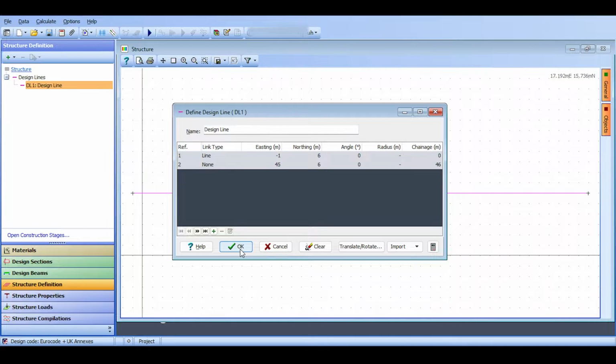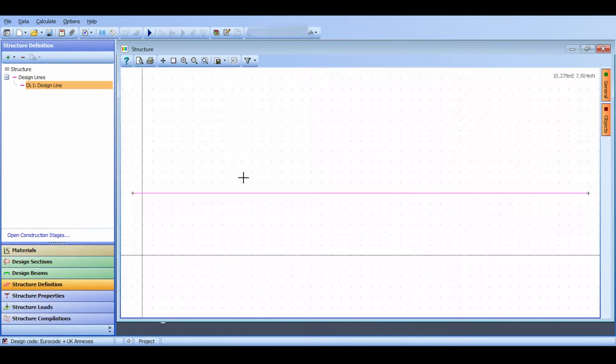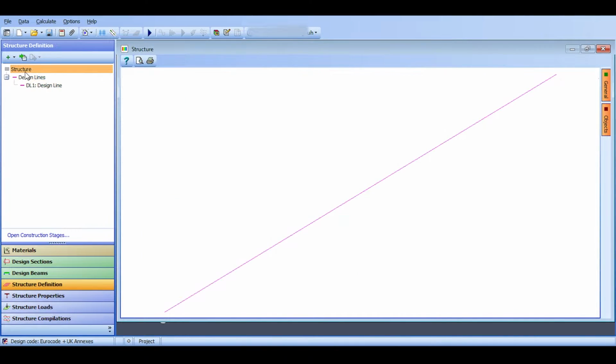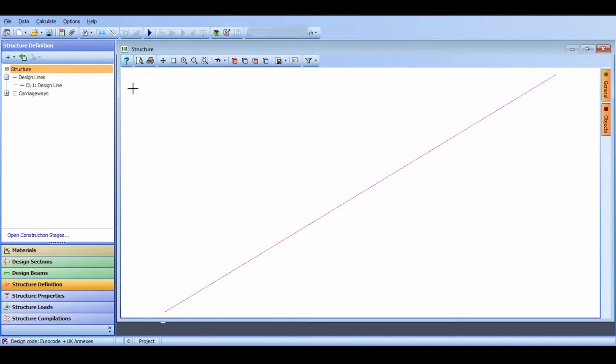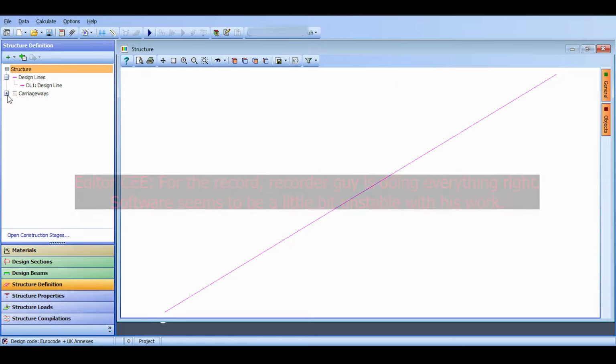You need to click OK here, because if you don't click OK, it will delete everything. I click OK here, and now I have my design line. If you right-click again on Structure and click Add, you can see that the carriageway option is now available, because you have defined your design line and now you can define a road on that design line. If you click on carriageway, it will...